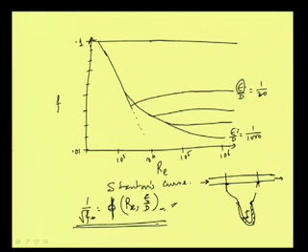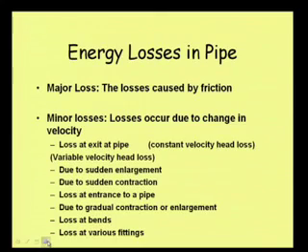So, if we do that, then we will more convincingly get the friction factor value. Well, I tried to emphasize the value of the friction factor, and the reason is that energy loss in a pipe we generally divide into 2 parts. One is major loss, another is minor loss, and the major loss basically comes from the friction loss. So, that is why if we calculate this friction factor wrongly, our entire effort will go wrong.